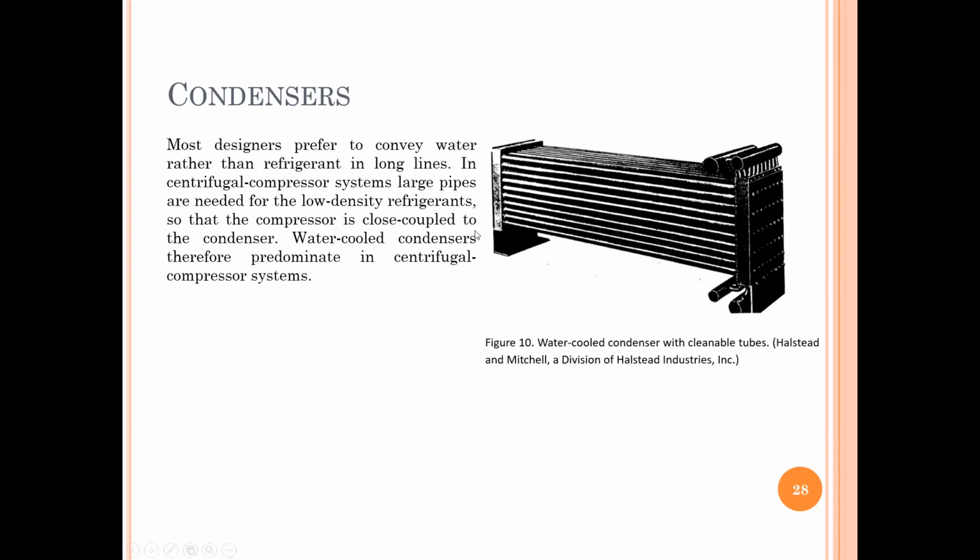Yan nga. In centrifugal compressor systems, large pipes are needed for the low-density refrigerants so that the compressor is close coupled to the condenser. Water-cooled condenser, therefore, predominant in centrifugal compressor system.